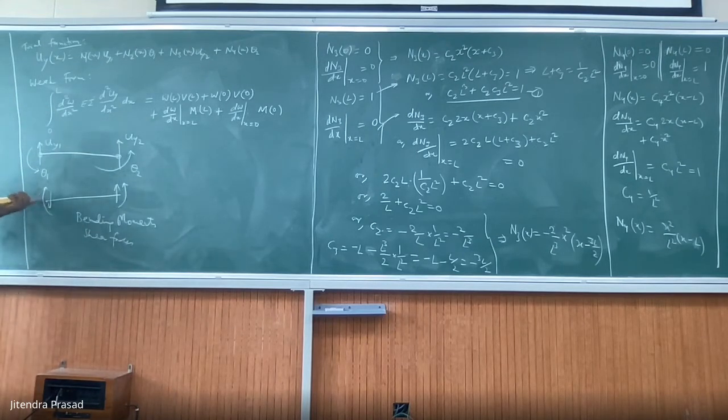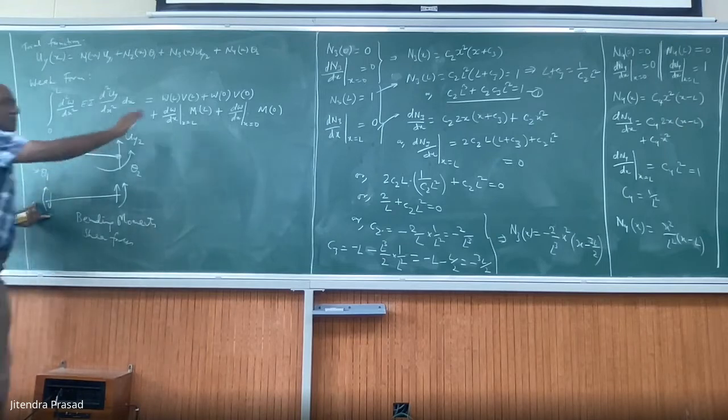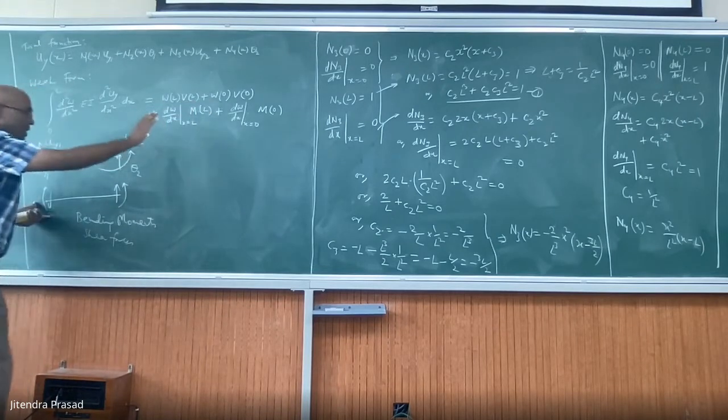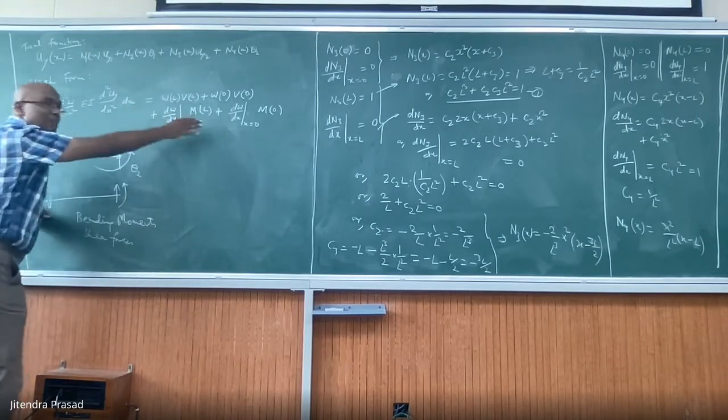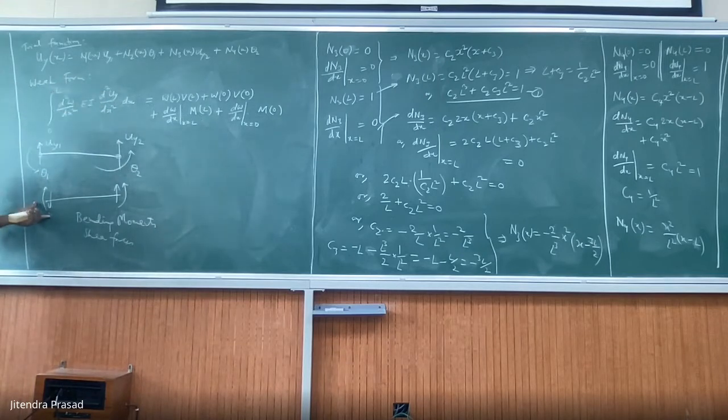But the actual force, if you consider this one, bending moment may be positive here, but actual moment is negative. When you are writing here, it is the actual force and moment we are talking about. So not to be confused with what is the shear force or what is the bending moment there. You don't have to calculate it back.